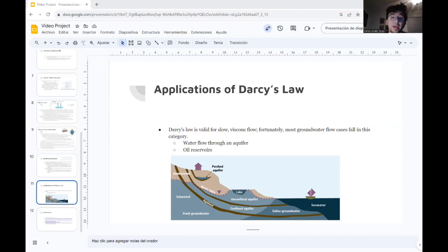The greater the pressure gradient through the same formation material, the greater the discharge rate. And finally, the discharge rate of fluid will often be different through different formation materials, or even through the same material in different directions, even if the same pressure gradient exists in both cases.